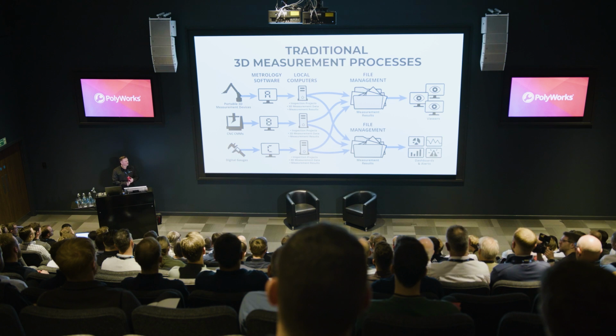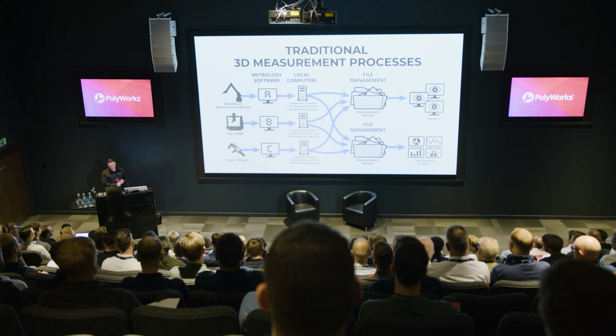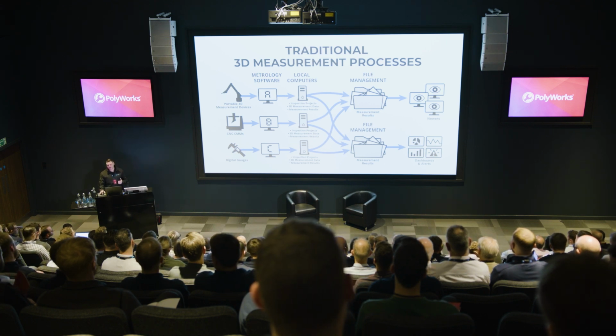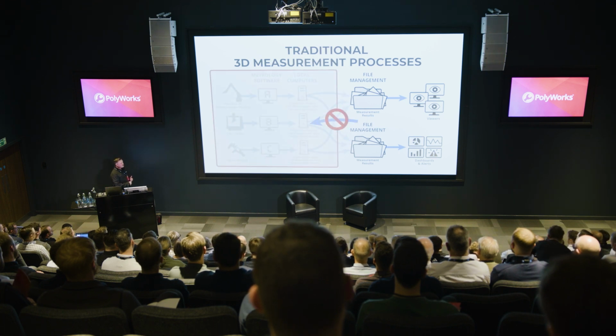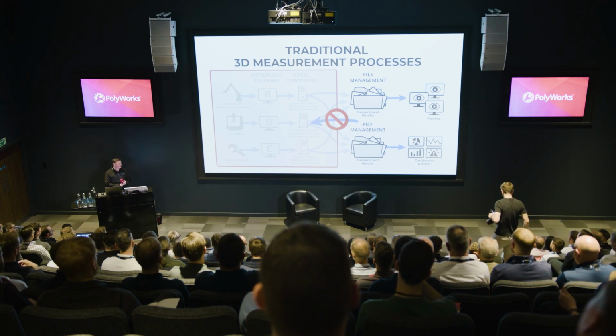The consumers of that 3D measurement data then manually take hold of that filing system and leverage things such as statistical analysis, taking those files into, let's say, Excel or Power BI, and so forth, to visualize that 3D measurement data in graphs, trend charts, monitoring key characteristics, and so on and so forth. Launching alerts when features are trending out of tolerance.